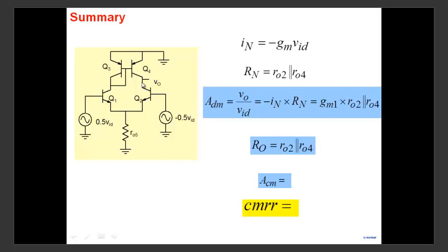But the result is going to be the same. So what you can do is, when you analyze, you can say, well, what is the resistance looking down, whatever I put here? And you put this point here, the common point, to ground. Okay? Whatever is the resistance looking down, and whatever is the resistance looking up, on this side, you put it to ground. And the final answer that you will get is the same that you get through more complicated analysis.